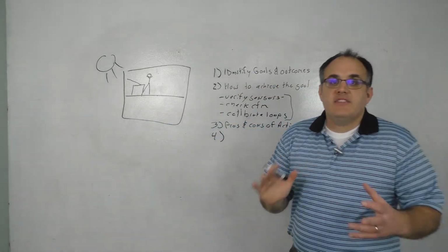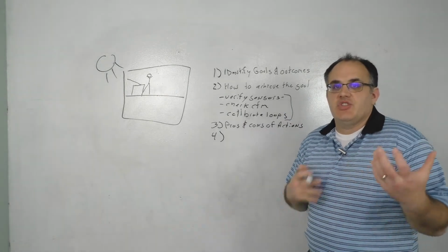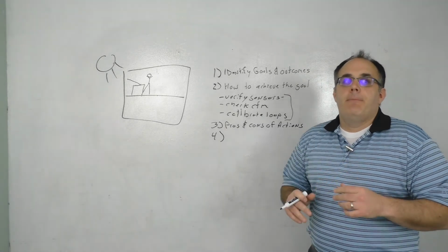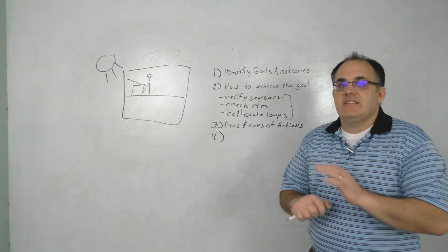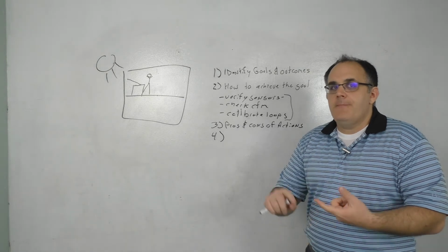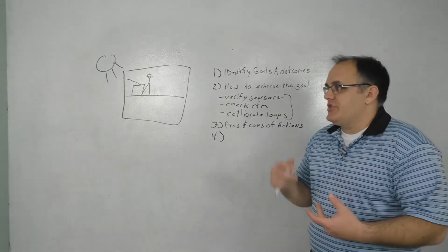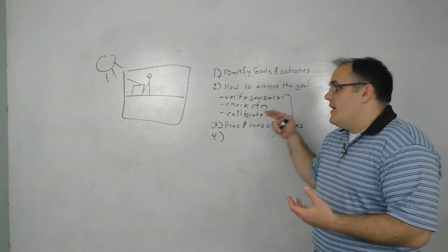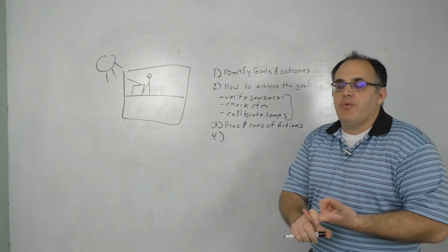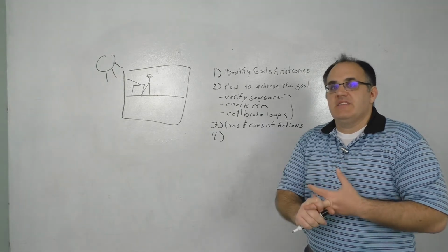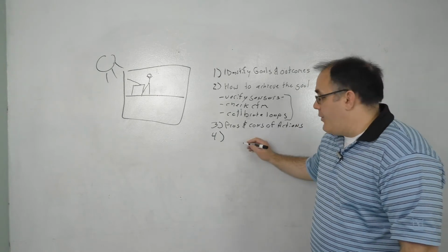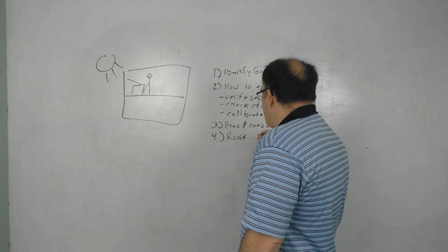That's number 3. Once you've done that, then you narrow it down, you start ranking the list. You look at the pros, you look at the cons, you look at the installed cost, yes, for those of you who are first cost thinkers, but you also look at the life cycle cost. This is something a lot of folks miss in capital events. They don't realize who's going to operate this. If we don't properly train and fund the operation of some of these changes, we'll just be back in the exact same spot a year from now, because we've not really dealt with the reason we're in this spot to begin with. Maybe it's a poorly trained operator. Maybe it's not having proper maintenance done because we're not properly funding our maintenance group. There's a variety of things we need to make sure we address, and that is how we are going to rank the items.